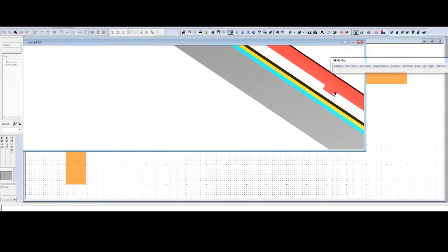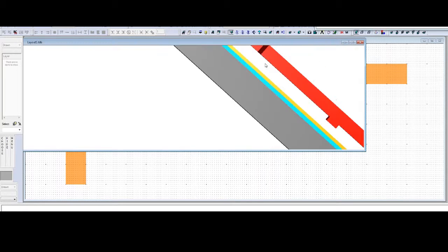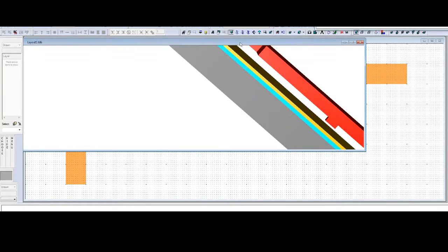So the dimple is actually there to keep things from sticking. That cantilever will come down and it'll hit on the dimple, but the dimple's so small, there's not enough force to let it stick. So it can come back up. If that dimple's not there, then that whole cantilever will come down and mesh, and it may not be able to become unstuck. And that's part of the release process. So I'll probably have a little lecture on that as well.